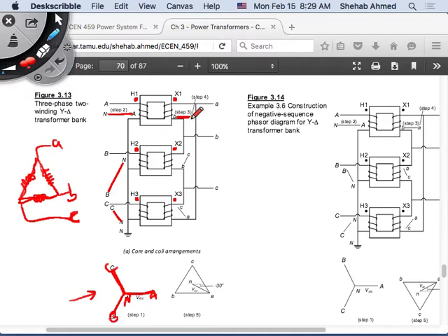Just look at the voltage, which has to be in phase. All the voltages will be in phase. So the voltage on the secondary side here will also be in phase, here will also be in phase. They're all in phase, right? But what are the various terminals that we have? So to label the terminals, and to know if these are my A, B, and C terminals, okay?